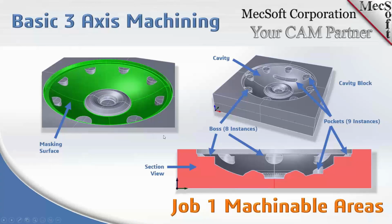And then on the right side, you see the green surface. We're calling that a masking surface. You can call it whatever you want, a reference surface or a guide surface. Basically, in the process of reviewing your model and what your approach is going to be to machining this, we decided that we didn't want the tool to go into these pocket areas at the top for finishing.